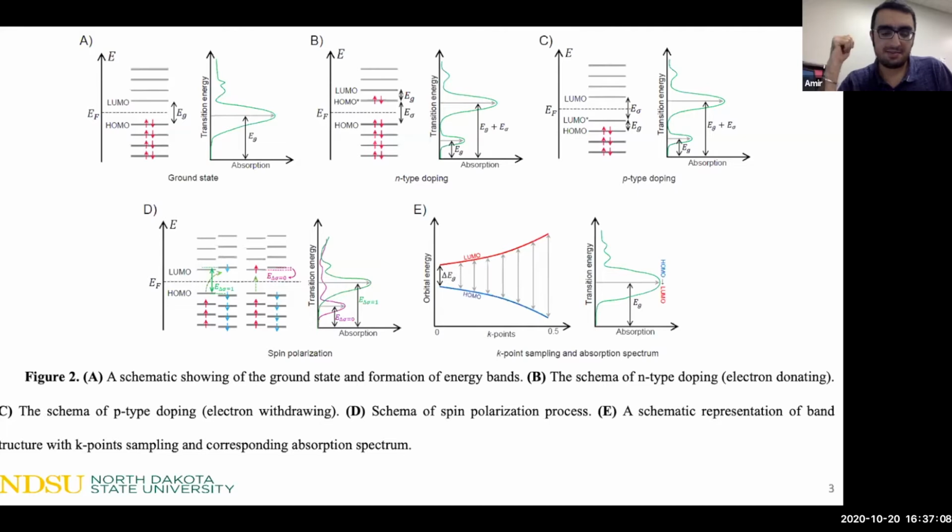As we inject maybe electrons or holes to the system, we expect to have some additional energy levels between the HOMO and LUMO, and change the HOMO and LUMO to new orbitals, in different energy levels. Here we did both N-type doping and P-type doping.